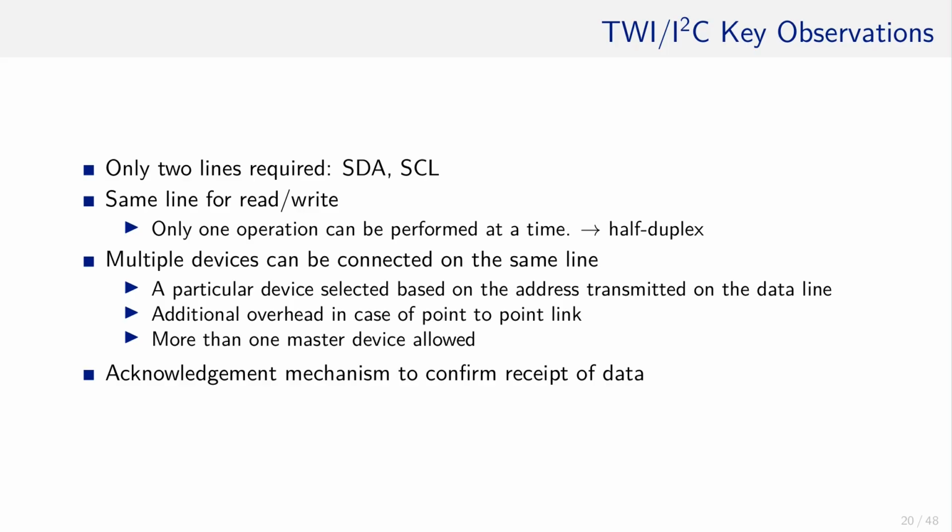However, compared to UART, which always comes in a transmitter and receiver pair and is therefore considered to be a point-to-point connection, I2C is a bus system and multiple devices on the bus are supported. And I2C has an acknowledgement mechanism that is not available in UART.